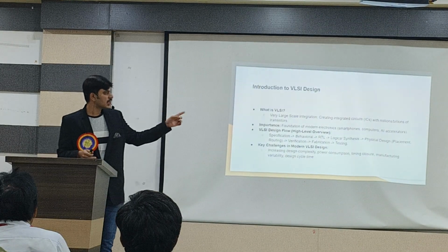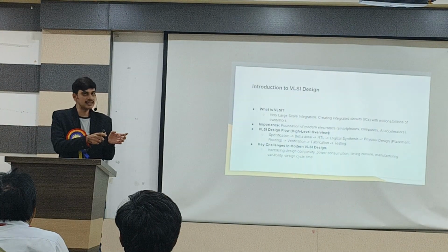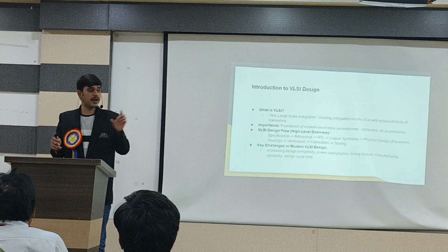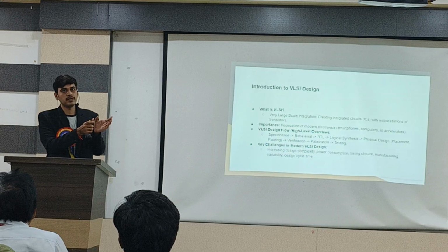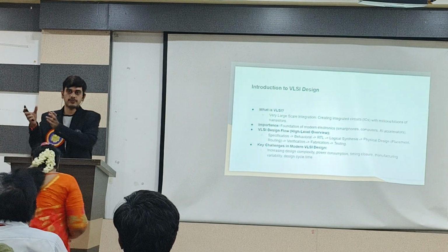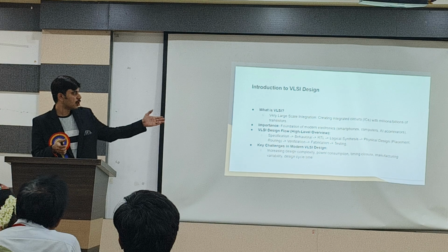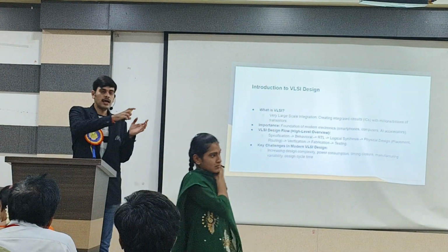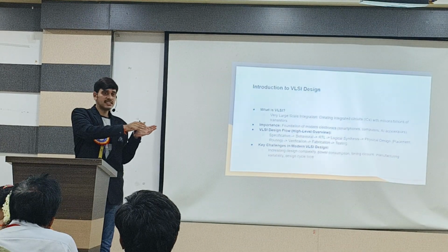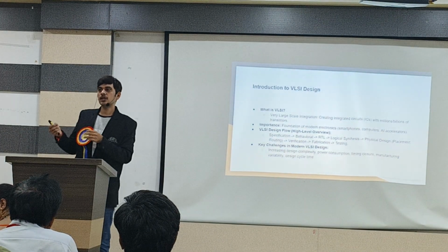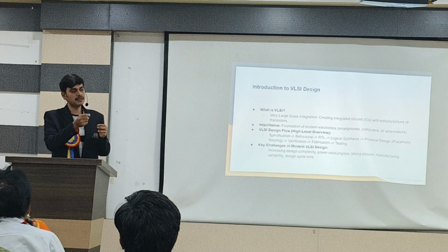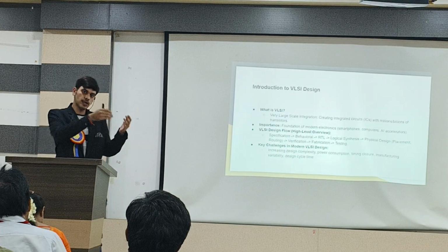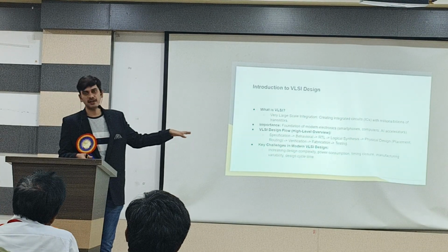From here, RTL goes through logic synthesis. So we just have gates, like generic gates: AND gate, NOT gate. These are all the gates we have. But in the RTL, we only have the regular program. So this code is converted into gates, and that's called logical synthesis. After synthesis, we do the physical design. Different logic gates are converted. Finally, a logic gate is a combination of transistors, so we transfer all the gates to transistors, and transistors to layout. This layout is done with the physical design.